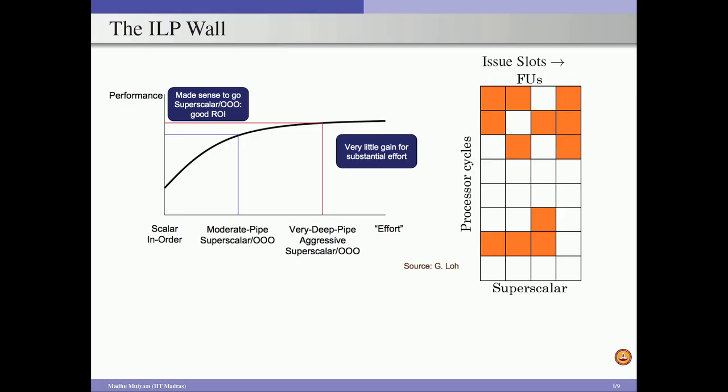As a result, unless we supply the data from the L3 cache for this load instruction, we cannot execute any instruction which requires the data supplied by this load instruction. So we may not be able to identify independent instructions that can be scheduled on these functional units in the appropriate processor cycle. Because of that, we will get a lot of cycles where functional units are not efficiently utilized. As we have more empty boxes, more functional unit cycles are wasted, and that in turn results in performance degradation.